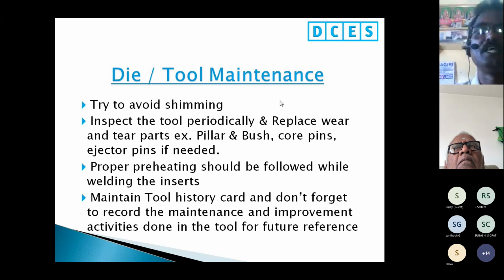Inspect the tool periodically. You should have a periodical inspection program, and replace the wear and tear parts, especially the pillar, bush, and the core pins. Sometimes core pin breakage starts. Remove all the core pins and change them. Otherwise, you will end up with many breakdowns and many losses. Ejector pins also: if you have any damaged ejector pin, it should be removed and changed.